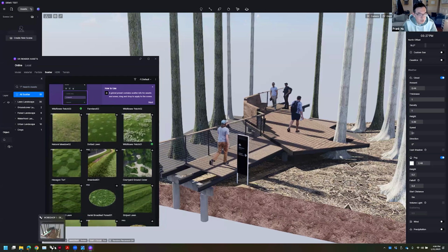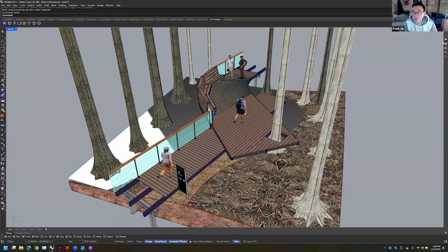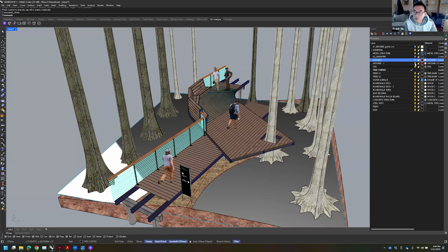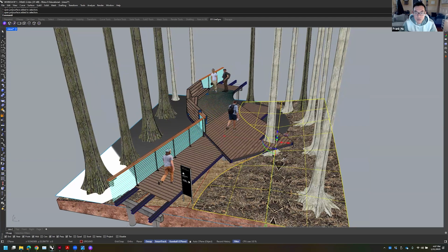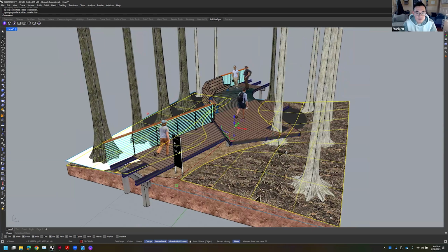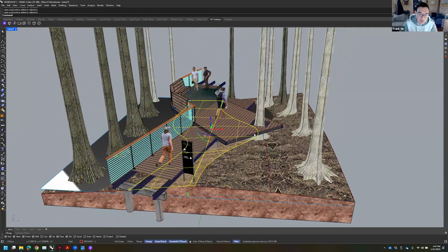And so the way that works in Rhino is that if you have a material associated with a specific layer, and as long as that material is different, you can basically populate that surface with a material. So what I mean by this is that in ground, I actually have two grounds. There's a ground 2 and a ground 1. You see how basically this is one surface, this is one surface, and this is one surface, because I want to populate a ground cover plant on just these perimeter surfaces here that I've selected, but not on this one here because that's below this elevated deck.